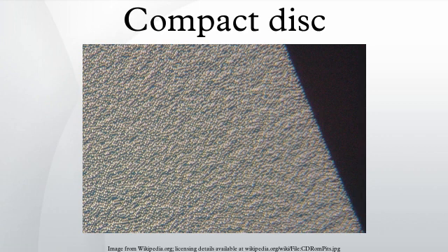An MP3 CD, however, can have audio file formats with mono sound. CD text is an extension of the Red Book specification for audio CD that allows for storage of additional text information on a standards-compliant audio CD. The information is stored either in the lead-in area of the CD, where there is roughly 5 kilobytes of space available, or in the subcode channels R to W on the disc, which can store about 31 megabytes.